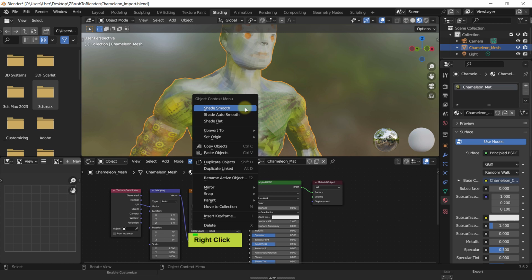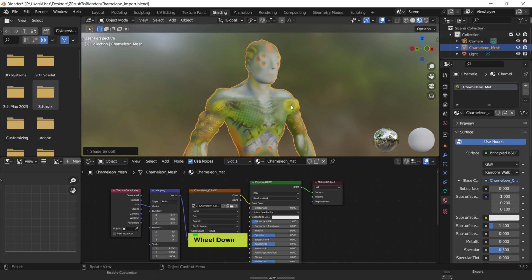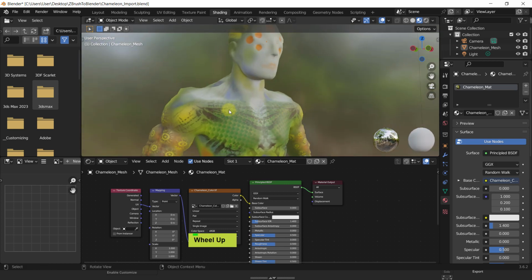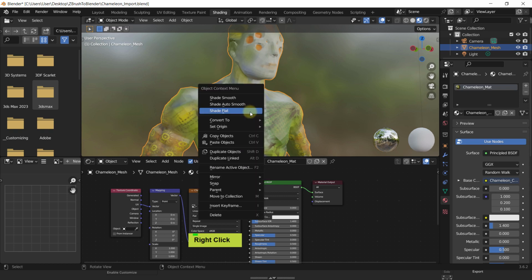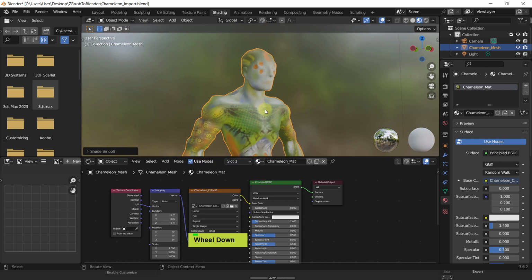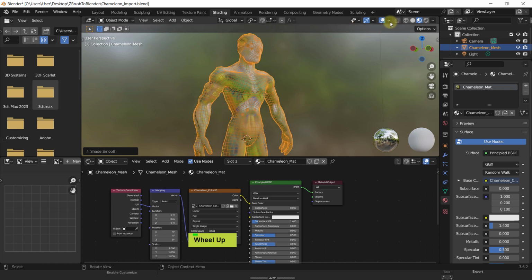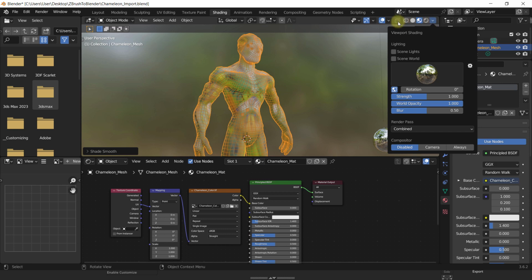But be careful, because we have to use shade smooth for sure, because otherwise the thing is faceted. Okay, so don't forget to use the shade smooth option. All right, so this is a simple single mesh. I have wireframe on quick preferences. Where are you, wireframe?